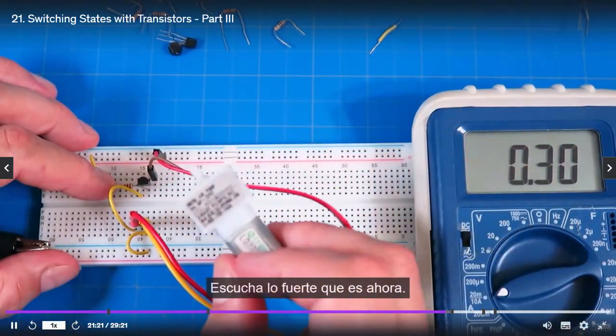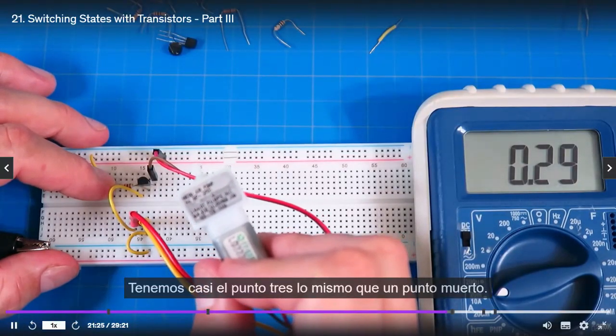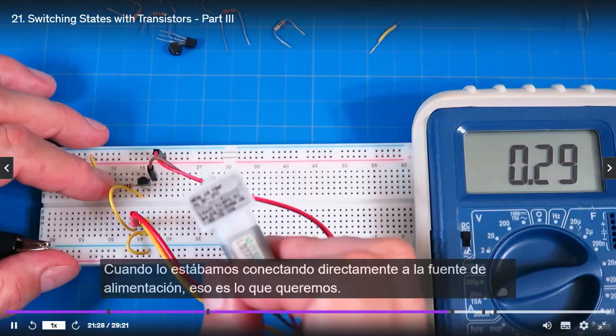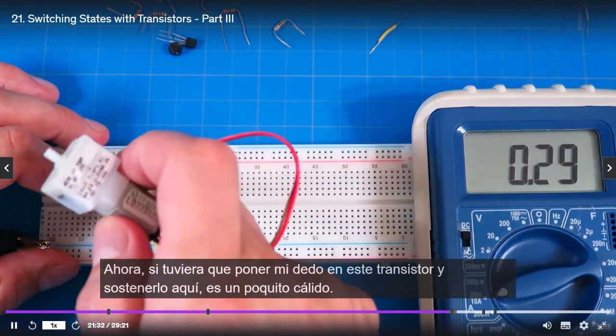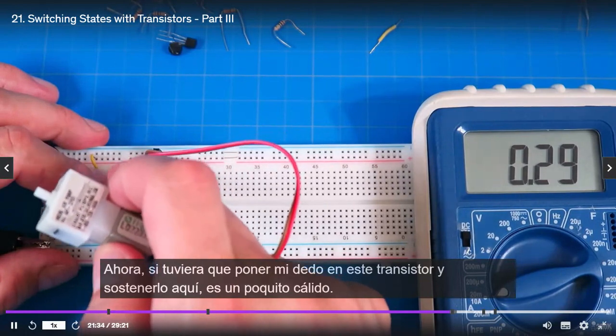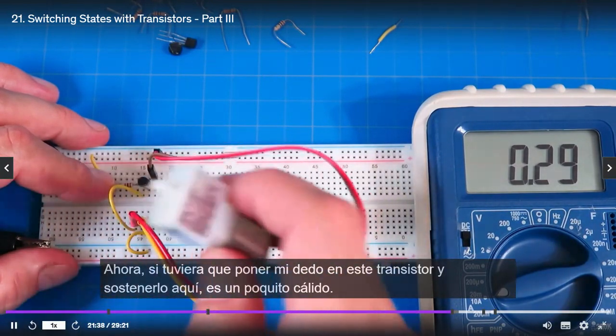There we go. Hear how loud it is now? And now look at our current. We've got almost 0.3, the same as a dead short when we were connecting it directly to the power supply. That's what we want. Now, if I were to put my finger on this transistor and hold it here, it is a teeny tiny bit warm, all right?